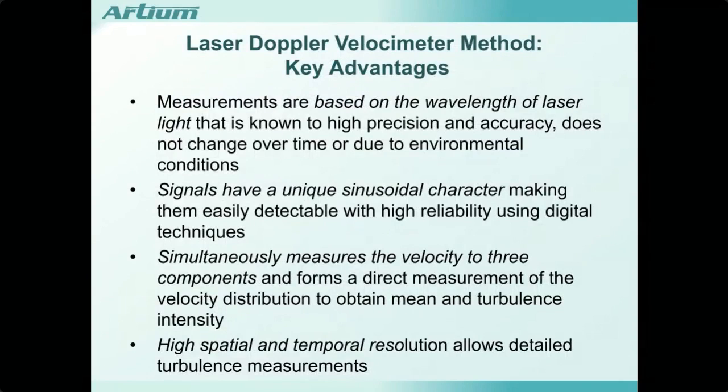Well, what are the key advantages? And I like to point these out because I think they're critical or important to understanding the method. The measurements are based on the wavelength of laser light, and that light wavelength is known with extremely high precision and accuracy, and it doesn't change over time. So it's an ideal measurement scale for a number of measurements, not only fluid dynamics, but particle sizing, surface speeds, vibrations, etc.